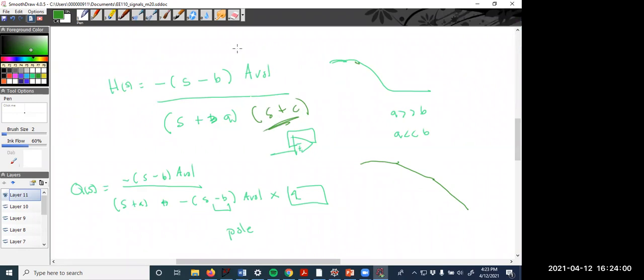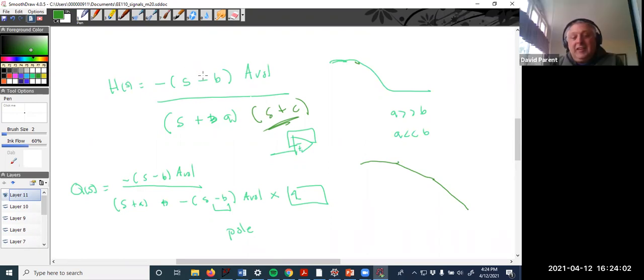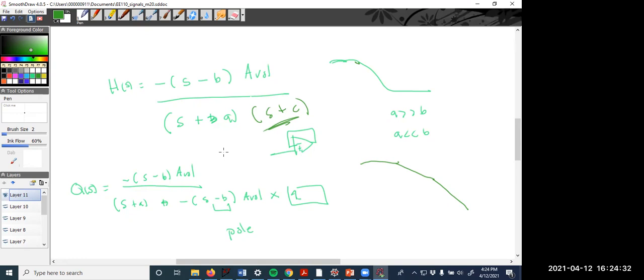But what I'm saying is that these kinds of things can cause issues when you simply hook it up. We have questions where hooking it up like this takes an overdamped system and turns it underdamped, right? But if the transfer function is like this, it can take an in control system and turn it out of control. So if there's an additional zero on the top, then it will completely change it.